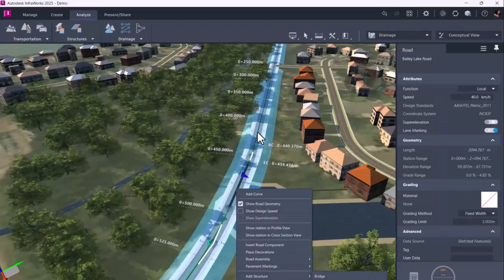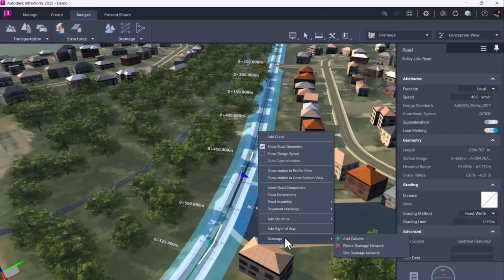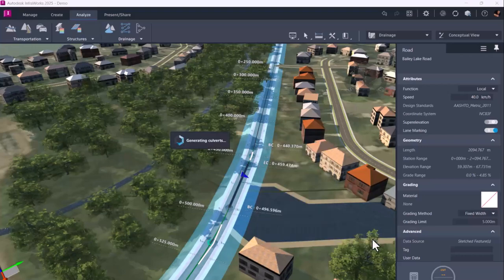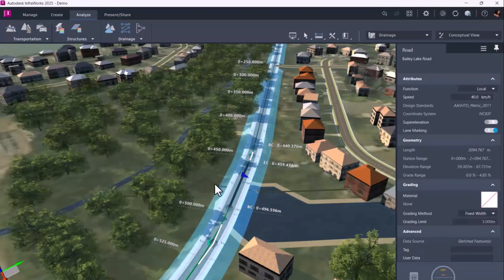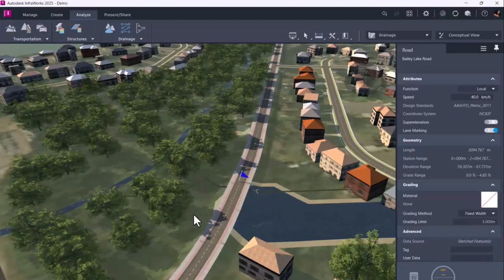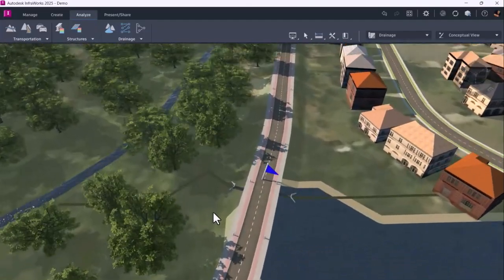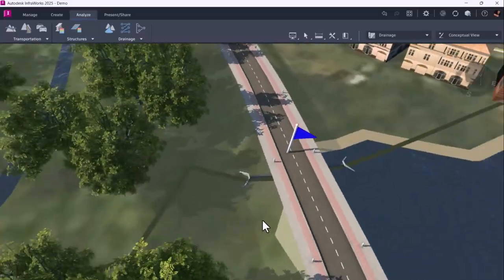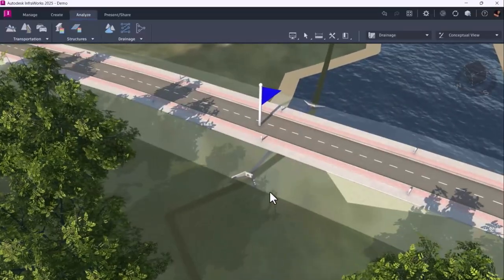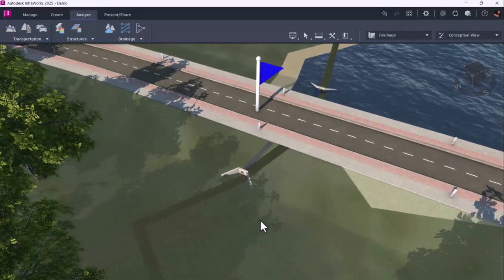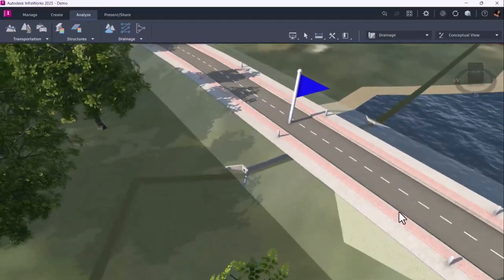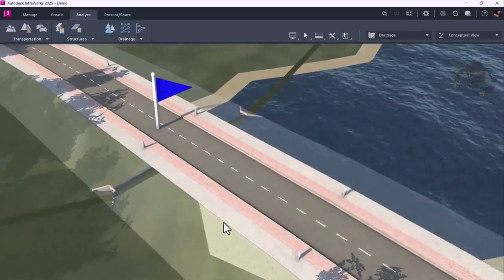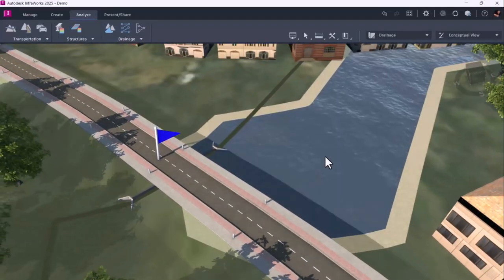And now to add a culvert crossing, literally all you do is right click on it and say, add a culvert. You don't pick the start point, the end point, put in elevations or anything like that. You literally just say, put in a culvert. It looks for the low point, it looks for that streamline that you can see ghosted in there, and it places that culvert there for us, which is great. So already done. Again, doing the work for us. We're just using the tools that are available. We're not having to go through and analyze or create or define anything up front.